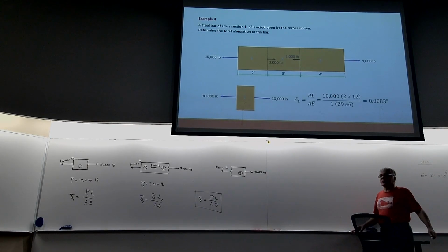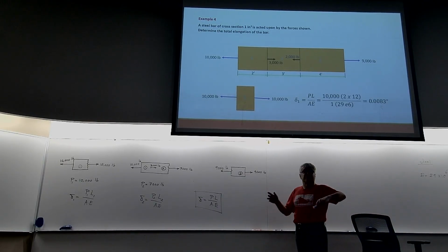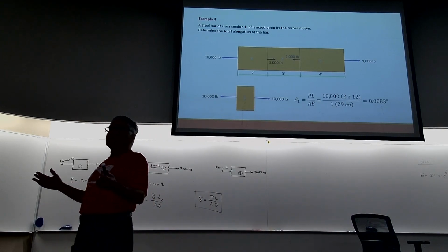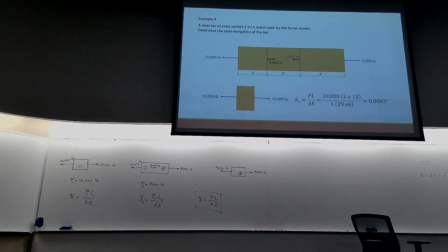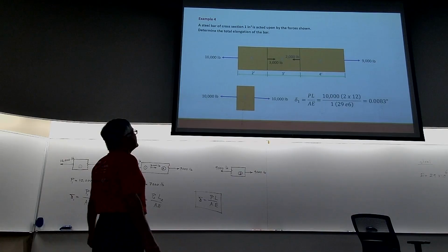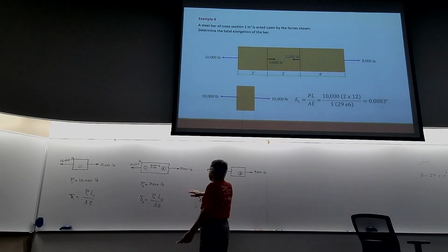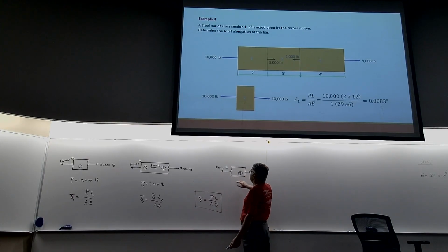And because we're using standard units for everything, we're going to find delta in standard units, which will be inches. So there is delta 1. Then we use the same equation using P2, L2, and P3, L3.